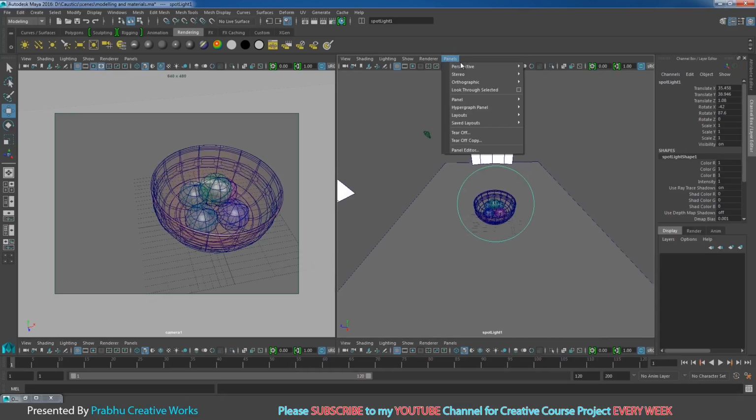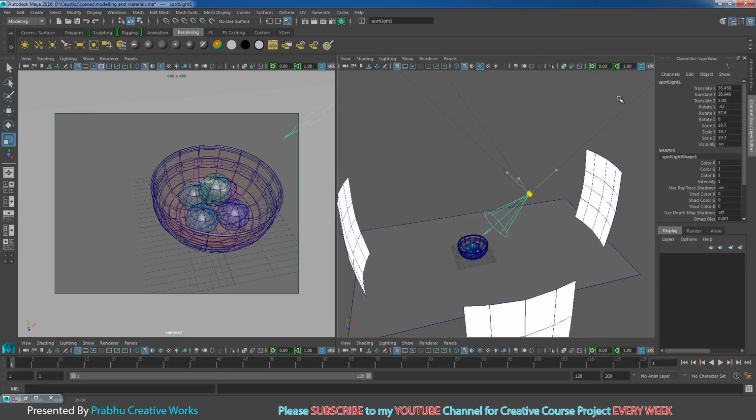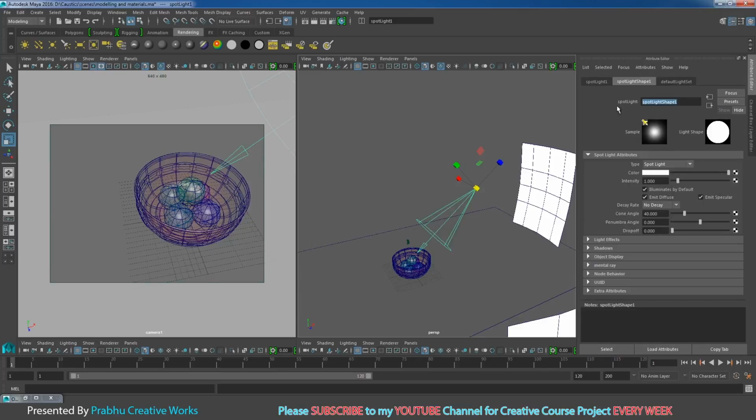Go to panels, perspective, and choose perspective. Press R and scale. So this is my caustic light. Go to the attribute editor. I want to rename this as caustic spotlight. I will set intensity to 0 and press enter. I don't want any intensity, because this spotlight is only for our caustics.